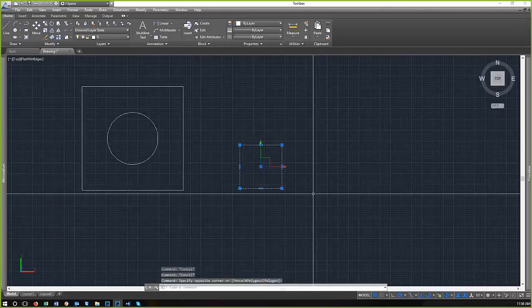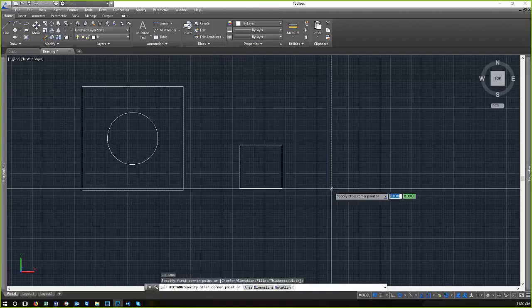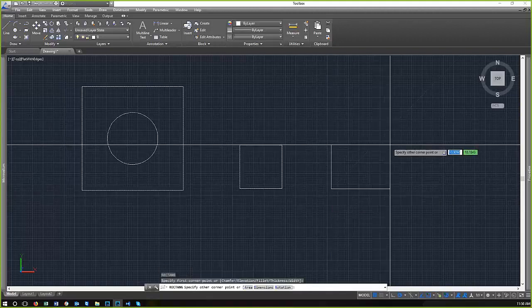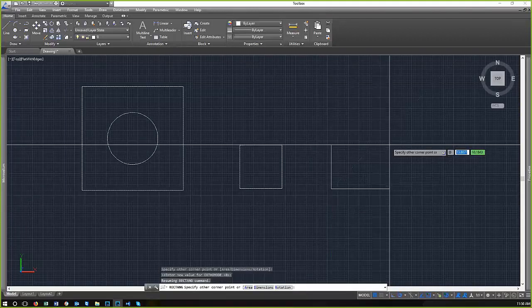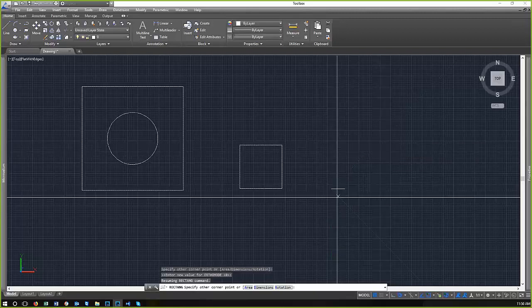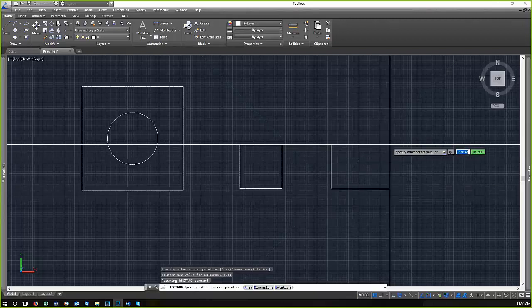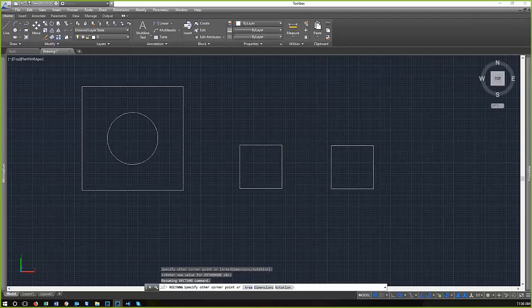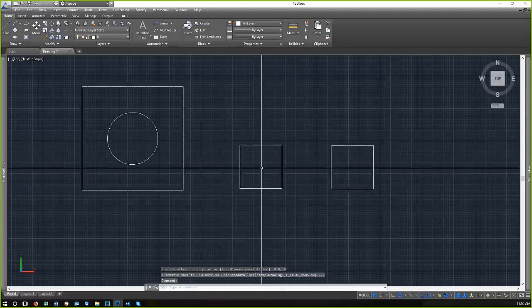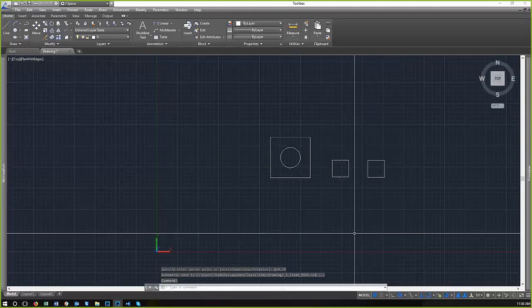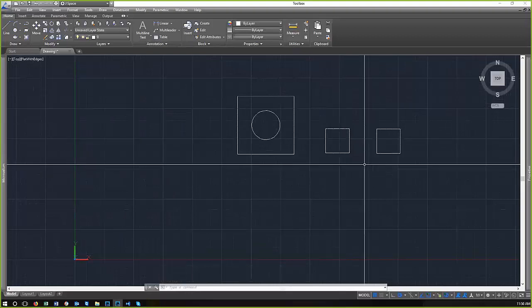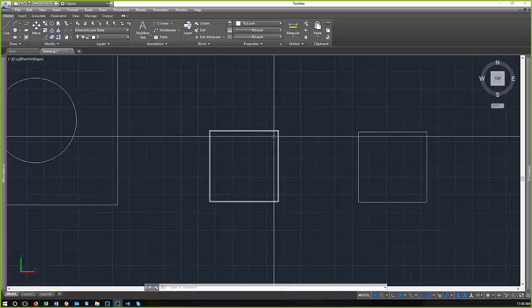If you're using older versions of AutoCAD, what you have to do is you click, and then you'll say @ and then type in what you want. So you're saying that this point is going to be relative to your first point. So I'm going to say @ 10, 10, and it's actually going to give me the same result. So that's not as useful as it used to be, because they seem to have noticed that and fixed it